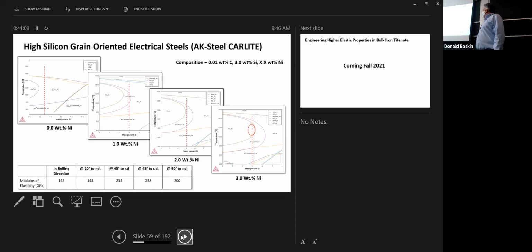So the problem with silicon, though, is if you add silicon, you make it more difficult for the material to be austenized, as we showed in the previous slide, right? It's harder to austenize. So if you can't austenize, you can't quench to get martensite. So one thing we have to know, for example, is that nickel will decrease the temperature for austenizing. And this is just an output from Thermo-Calc that shows that as you add nickel to this high silicon steel, they call this the gamma loop or the austenite loop. It moves, it elongates. So this is just showing that if you wanted to make this material and you wanted to strengthen it, and you wanted to stiffen it, you would lose strength because you couldn't austenitize and then make it into martensite. You could get that capability back by adding nickel. How much would you have to add? That's what Thermo-Calc is good for.